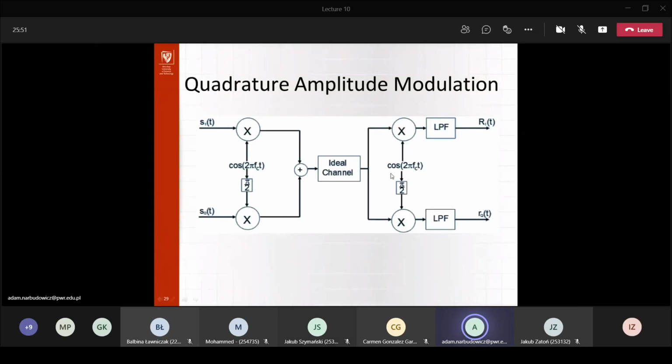Here we'll meet part of the sine and part of the cosine, and here we'll meet the other part. There'll also be different components of that signal. However, firstly, it is not significant in this context because they will still be orthogonal. So what you would observe, if you think about the QAM diagrams, is that the diagram simply rotates by a certain angle.